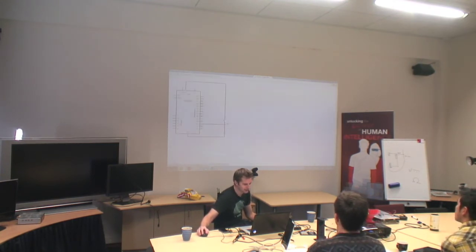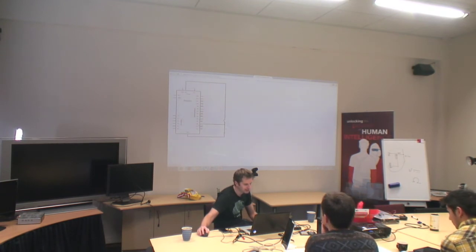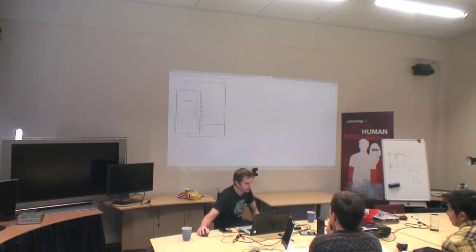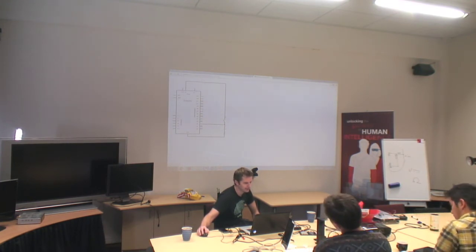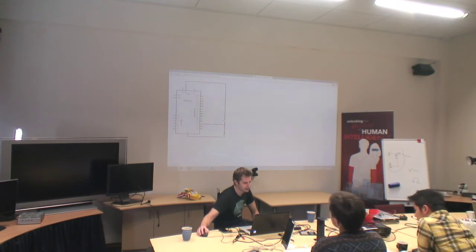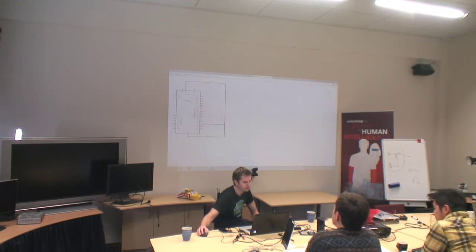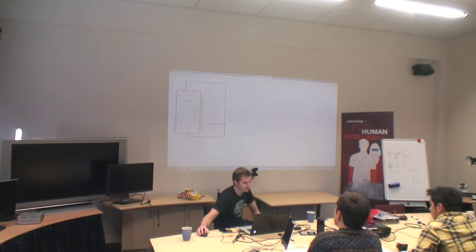So this is the schematic for it here. Basically we have D2, our digital pin that we're going to use to check the voltage. It goes out and connects on one side to the switch, which comes from 5 volts. So 5 volts goes into the switch, then across this line, into a resistor, and to ground.